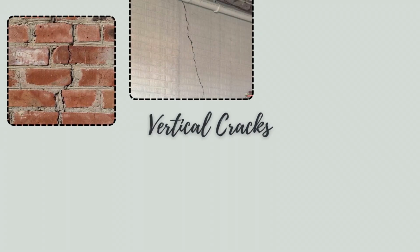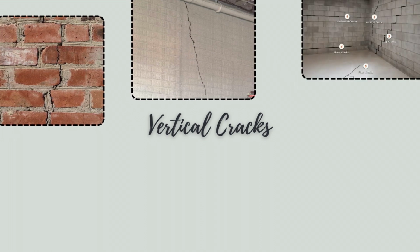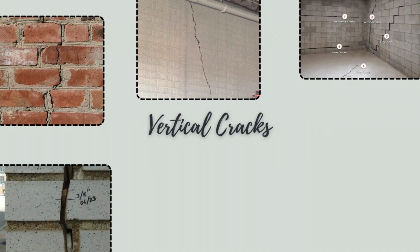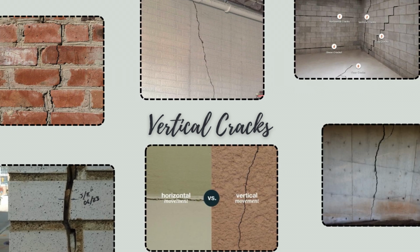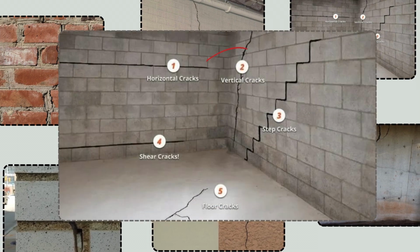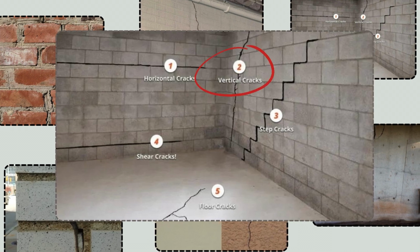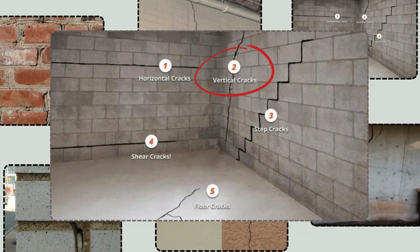Vertical or nearly vertical cracks are only structurally related when there is lateral movement. This assumes the crack is consistent in width from top to bottom. In most cases, vertical cracks are relatively narrow, even those running from top to bottom and caused by contraction. Expansion and contraction are normal for building materials. The more rigid the material is, the more likely it is that the crack will develop. Porous or less dense materials will be flexible and less likely to crack.